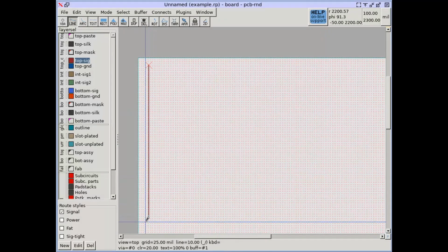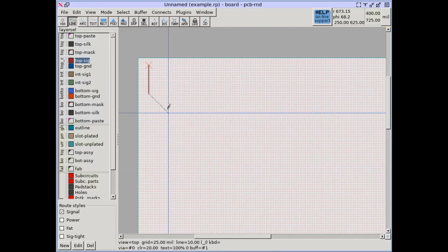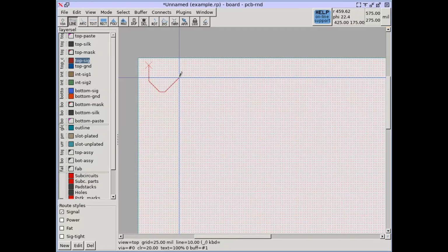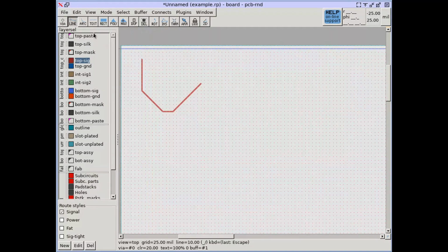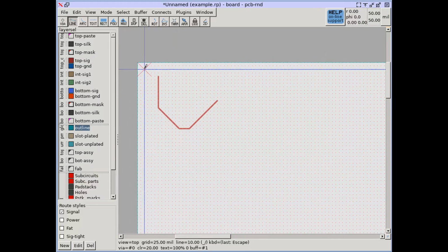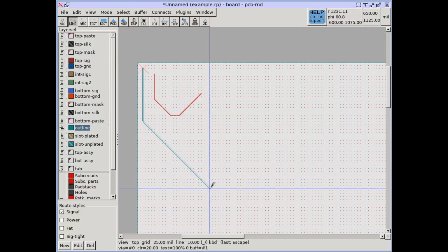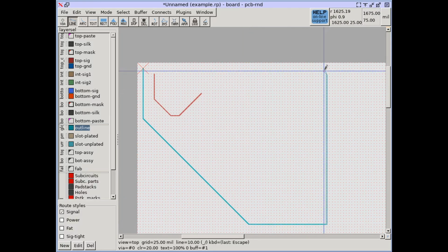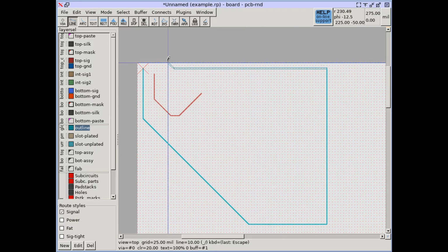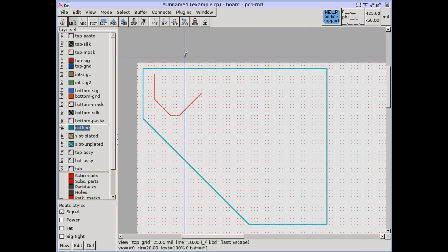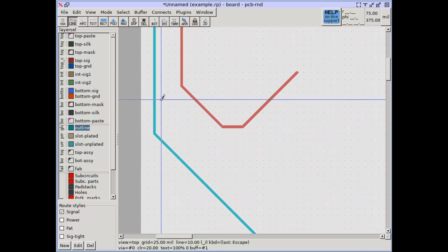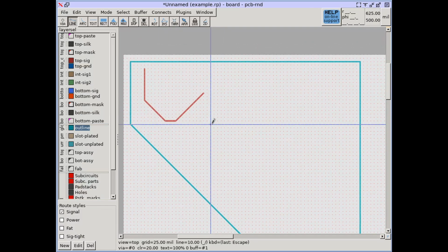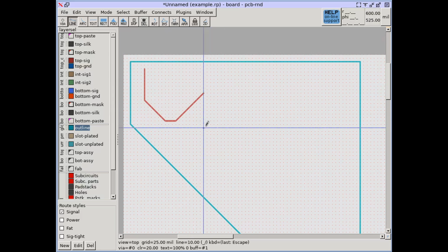Board fabs may cut around the board shape using different technologies, ranging from routing to sawing or V-cuts. The most common method is routing, but the board designer doesn't know the diameter of the tool used by the fab. Best practice is to use thin lines on the outline layer to draw the shape of the finished board. The common interpretation is that the centre line of this line will be the edge of the finished board.